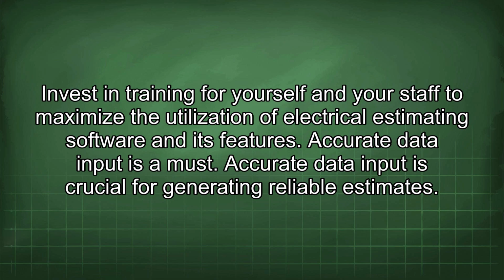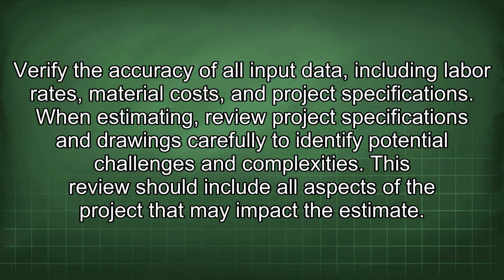Accurate data input is a must. Accurate data input is crucial for generating reliable estimates. Verify the accuracy of all input data, including labor rates, material costs, and project specifications. When estimating, review project specifications and drawings carefully to identify potential challenges and complexities. This review should include all aspects of the project that may impact the estimate.